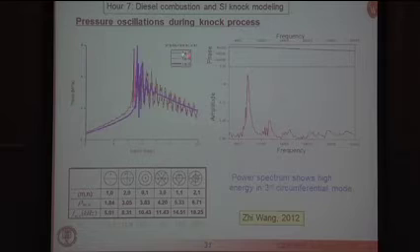Notice there are 3 different curves here. They correspond to the use of 3 different time steps in the simulation. So you need very small time steps in order to catch these high-frequency waves. Here are Draper's resonant modes again. You see there's a sloshing mode here. Then there's a mode where you have basically side-to-side oscillations. Here are the radial modes, and so on. And each of these corresponds to a different frequency component of these oscillations.